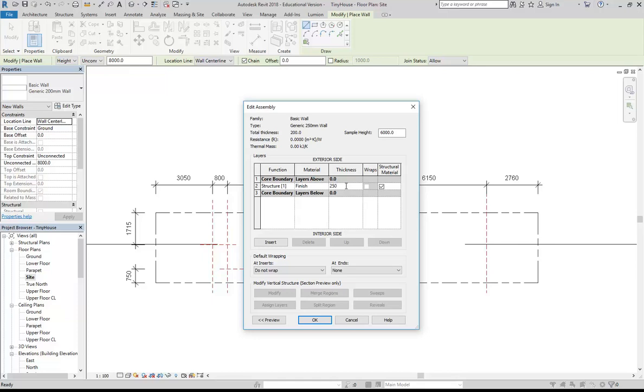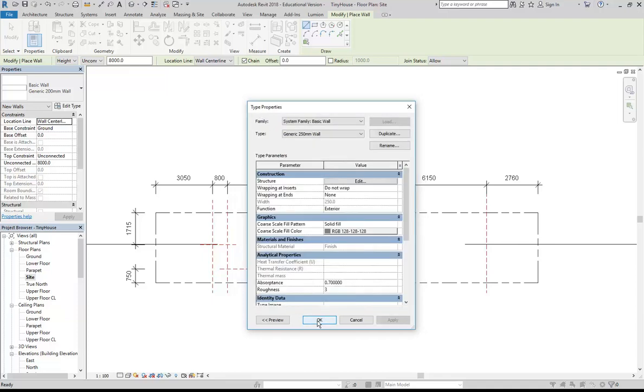If it was a proper cavity wall, which the slightly later buildings would have, then it would be 290, because they're going to be 270 for the cavity brick wall, and then 10mm either side to give us 290. So you should be thinking about that when you see these different wall thicknesses. So again, this is 250. So if again we click OK, I've set up my new wall.